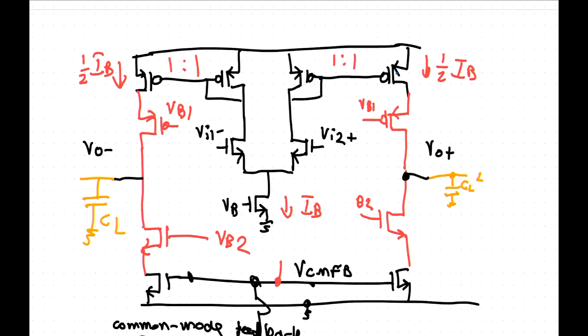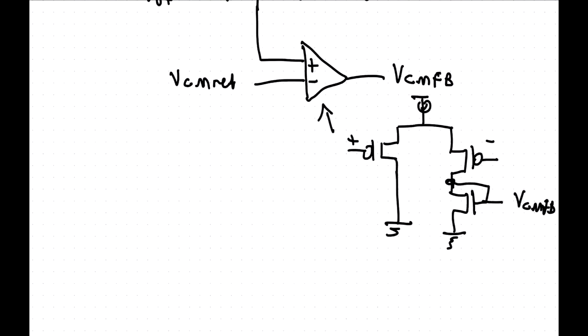There's a number of different ways that you can address this. I think probably my preferred way is just to put in a source follower to drive those resistors. Okay, it's fine. You're going to lose a little bit of range, but not very much. So we've got to have a differential pair to compare the common mode with the target common mode.